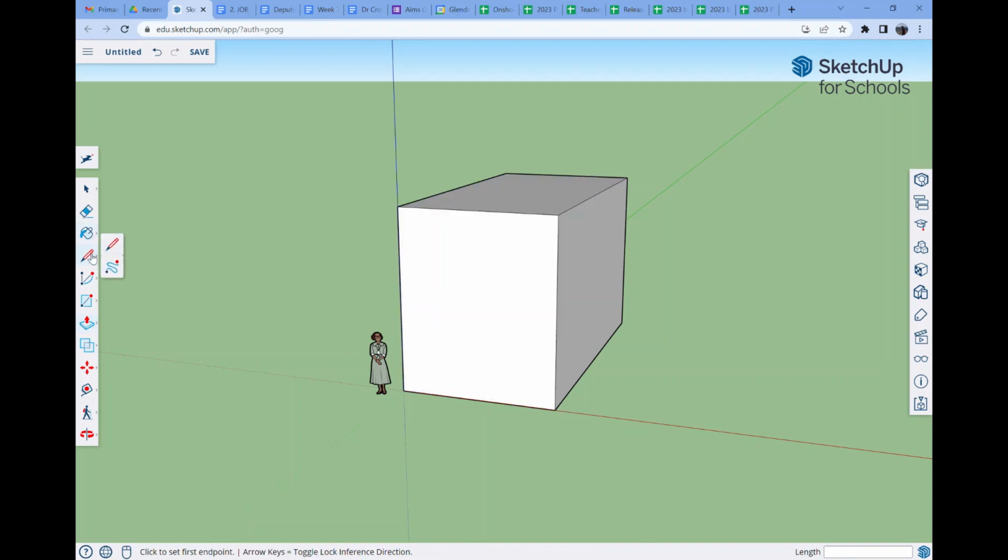And then I'll use my pencil tool here, and remember the side of the roof is 4 meters high, so what you need to do is find 0.8 of a meter down from this top corner. So I'm going to measure down and just draw a little line that's 0.8 of a meter. And that will help me now, because my pencil will jump onto the end of that line. I can go up to the midpoint, and I can go like this. Okay, so there's a little line there. You can't see it, but it helps you to draw the pitch of the roof.